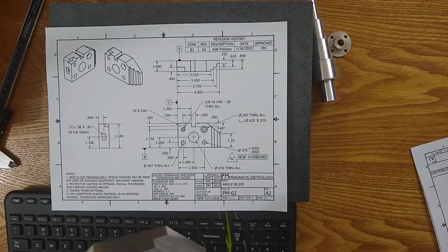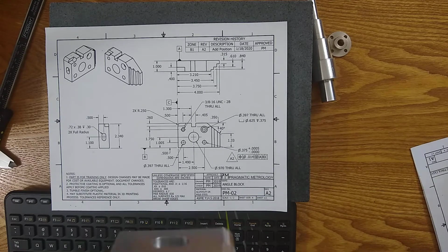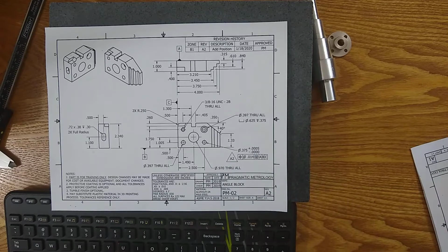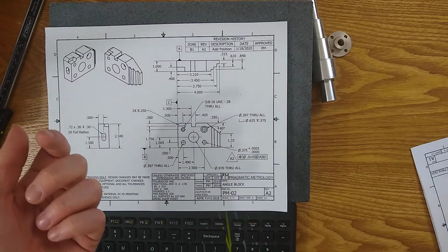Sometimes when you're manufacturing, you're really pushing the limits of what's capable in terms of design, and the machining might punch through when the design didn't intend for it because it's such a small sidewall that gets left over. So you'll want to look for that, because it might be the machine did exactly what it was supposed to do, but the tip just pokes through.